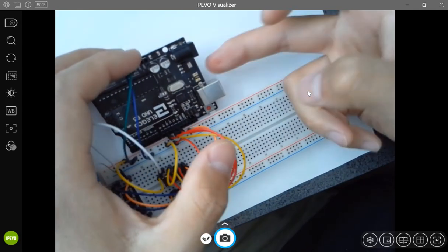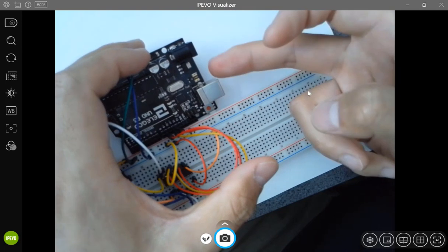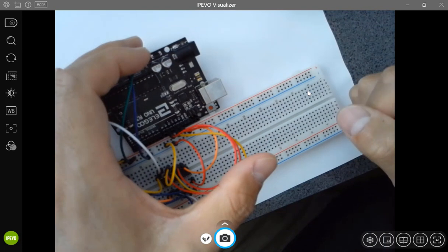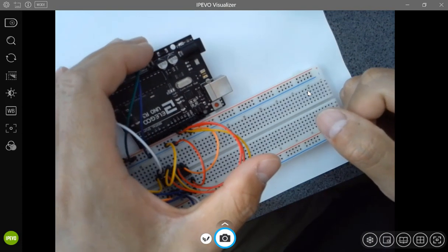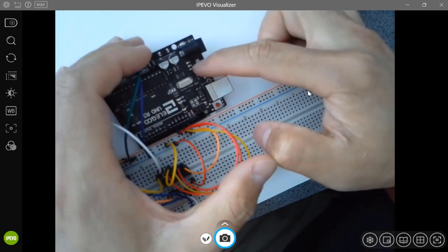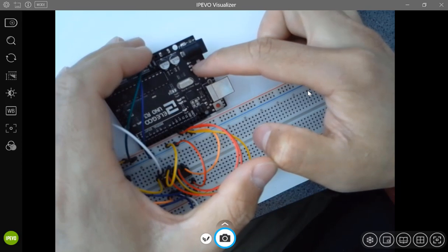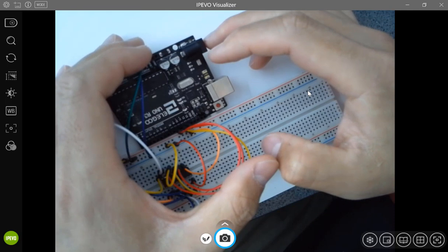So if you have an 8 volts DC power supply, you plug in, you get 5 volts. If you have 12 volts, you get 5 volts. If you have 4 volts, you get 5 volts. Really? If you have 4 volts, can you get 5 volts? No, this is a buck converter. It only steps down the voltage. It's not a boost converter. It cannot boost the voltage. So 4 volts won't work. You need at least 6 to 7 volts.